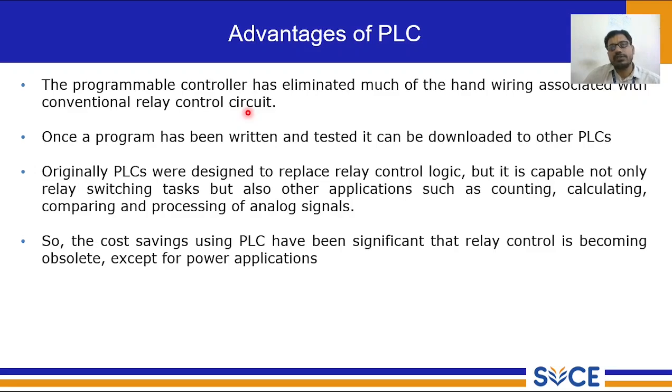Programmable logic controllers were mainly brought into the field to eliminate this relay circuit. Once a program is written and compiled, as we say in programming, or tested, we can directly download it to the PLCs, and the same program can be downloaded to other PLCs in the control level of automation.